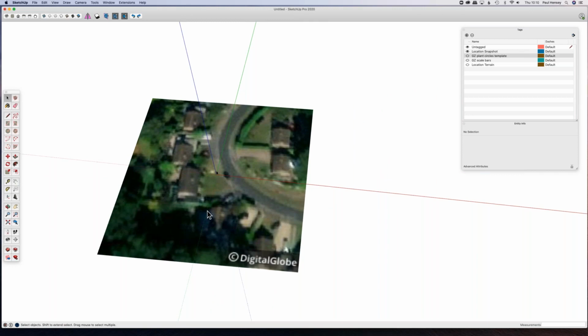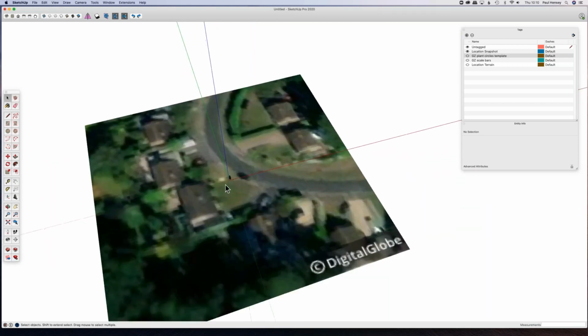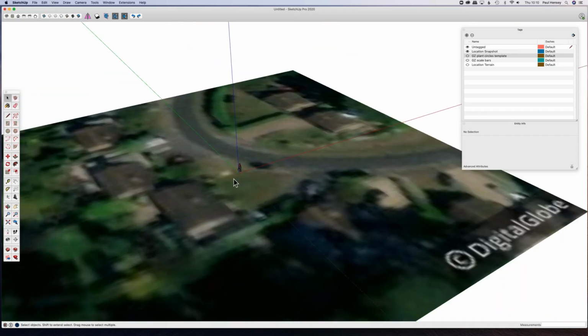The default north in SketchUp is along the green axis. In a previous session, I've talked about changing that default using the Solar North plugin. This has by default reprogrammed SketchUp. So the geolocation function takes the default position of the axes, which is probably in the car park outside SketchUp HQ in Boulder, Colorado, and repositions it to the center point of your postcode. So now we can do correct shadows and all of those sorts of things for Sussex rather than Colorado.